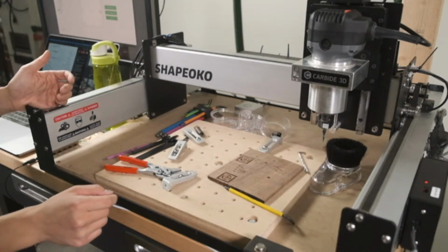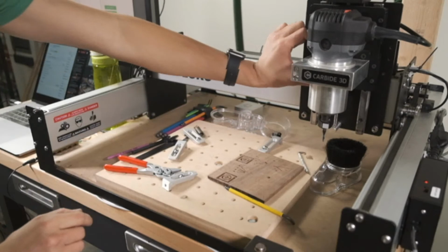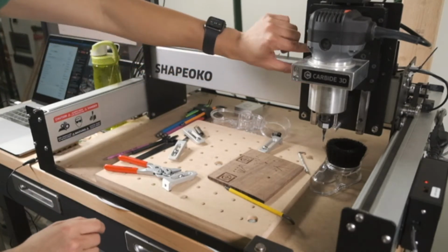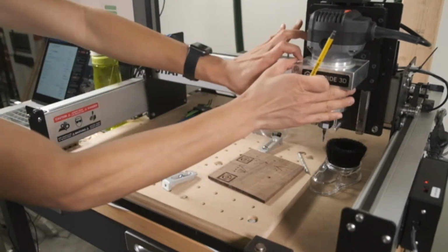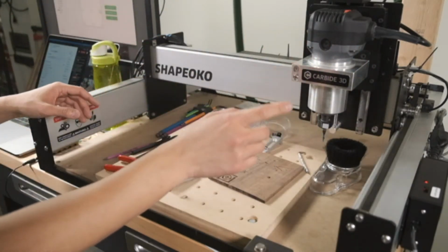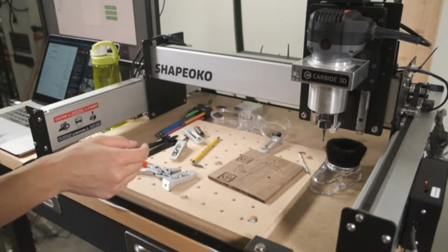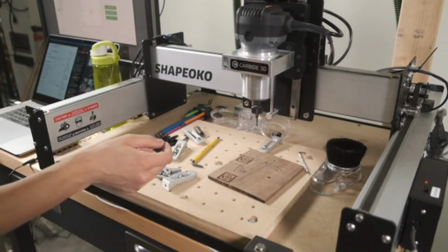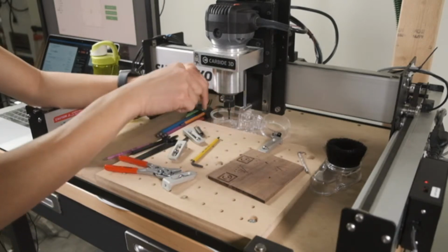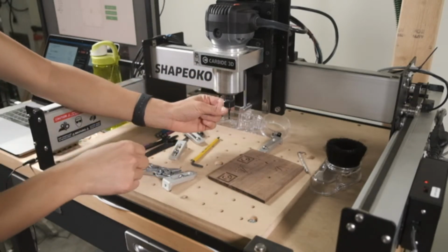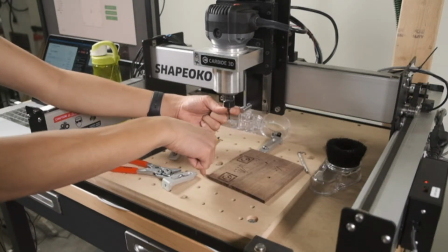The way I like to fix this on the Z Plus or the HDZ, where the spindle is mounted to a plate, is to loosen 4 screws and just set this straight. There are tramming tools you can buy that cost like $100, which is more than I like to spend. So usually what I do is take a piece of wood with 2 1/4-inch holes drilled in it, stick an end mill in here, clamp that piece of wood on that side, and stick an end mill or a pin on the other side.